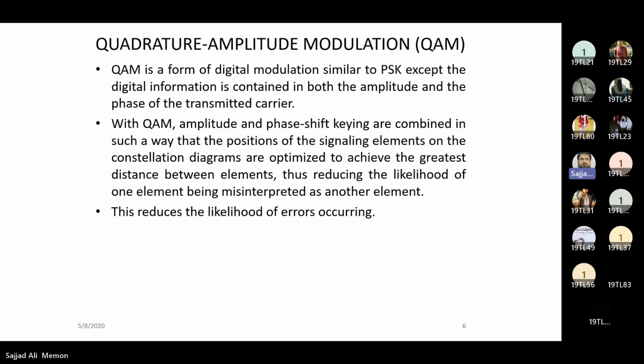If any shift greater than 11.25 degrees comes in 16 PSK, then the receiver will not be able to understand the symbol information, because PSK modulates the information in the phases, and if phases shift so much that the receiver couldn't understand it, then there is no point of using PSK as a modulation scheme. So with PSK, we have to be very careful in choosing the order of the modulation scheme.